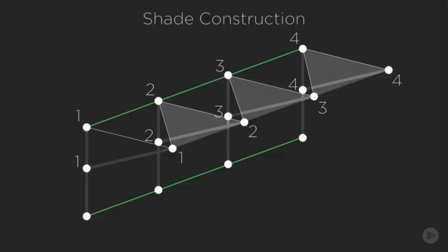A loft essentially stretches a surface between two lines or edge curves. To keep it simple here in the Dynamo environment, we're going to create a line from the top of your mast to the endpoint of that mast's associated boom arm. The next step is to stretch a line from the mast's endpoint at the top to the adjacent boom arm endpoint.